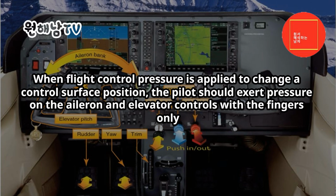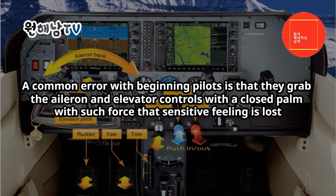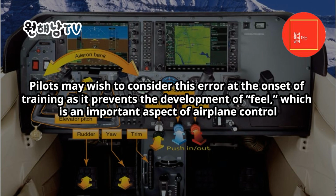When flight control pressure is applied to change a control surface position, the pilot should exert pressure on the aileron and elevator controls with the fingers only. This is an important concept and habit to learn. A common error with beginning pilots is that they grab the aileron and elevator controls with a closed palm with such force that sensitive feeling is lost. Pilots may wish to consider this error at the onset of training as it prevents the development of feel, which is an important aspect of airplane control.